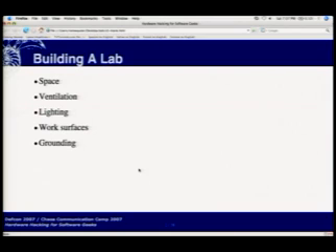So one way to start is an ESD mat and some grounding bracelets. And maybe a coat if you've got cats or whatnot, because even if you've got fur on the outside of the coat, it's of a material that's going to keep the static from building up on the fur and not going to short your devices.